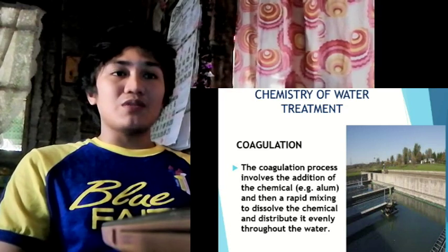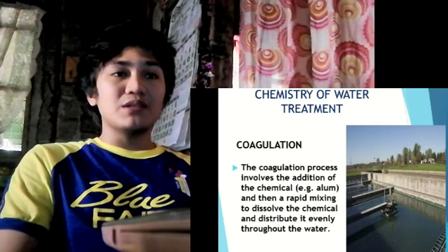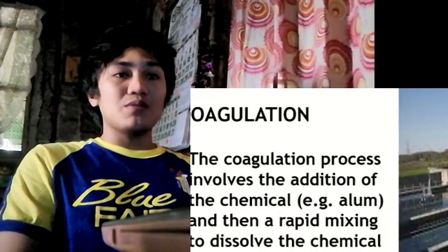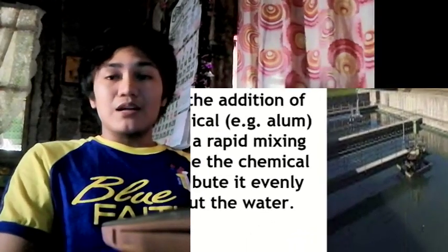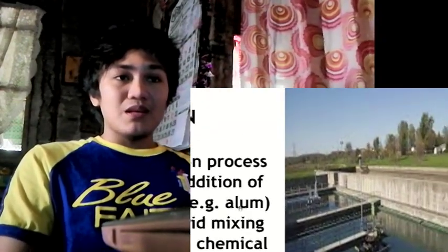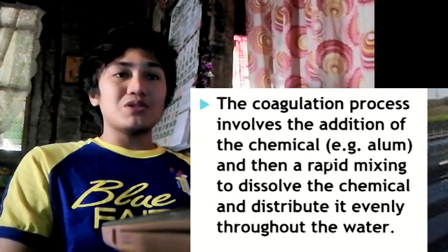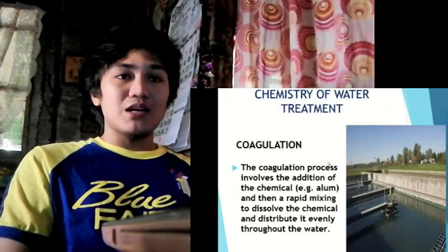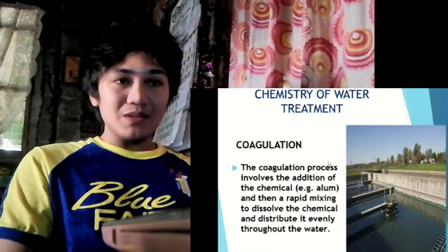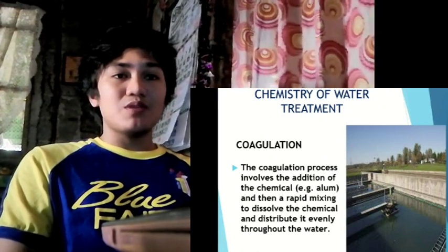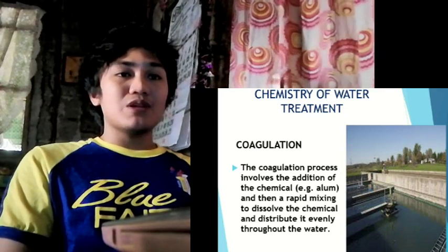There are three key properties of a coagulant. First is the trivalent cation, non-toxic, and insoluble in the neutral pH range. The trivalent cation: as indicated in the last section, the colloids most commonly found in natural waters are negatively charged. Hence, the cation is required to neutralize the charge. Non-toxic: this requirement is obvious for the production of a safe water. Insoluble in neutral pH range.